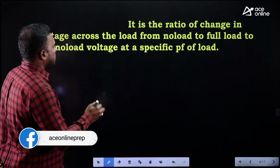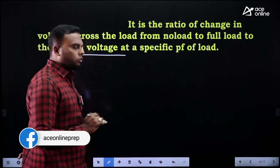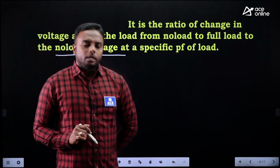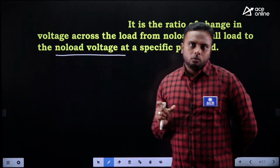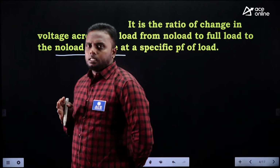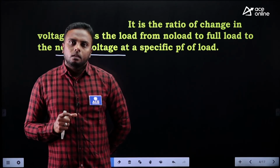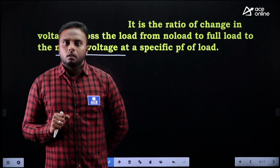And it is expressed as a ratio to the no load voltage, at a specific power factor of load, because we have different power factors like lagging, leading and unity power factor. Same as it is in an alternator also. Whenever the power factor changes, your regulation will change.